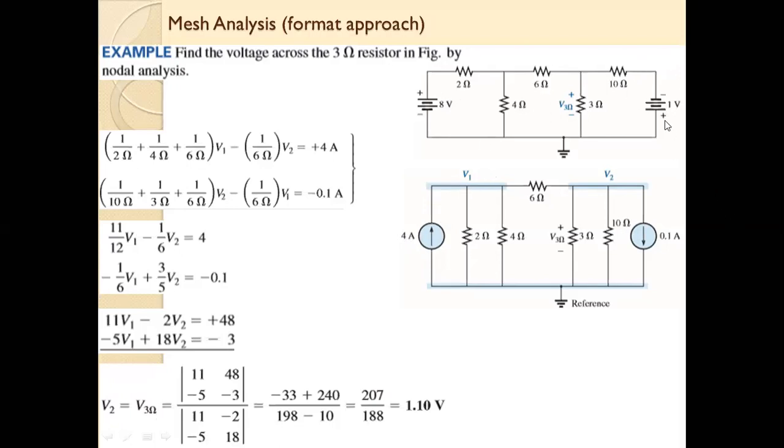Similarly, again here the voltage source is given. In this source, the conventional current direction is downward, because that is from plus to minus. So we will make the current source in parallel in the downward direction. And the resistor which is in series with the voltage source, we will place as it is in parallel. And the value of current would be found using I equals V divided by R. V is 1 and R is 10. So 1 divided by 10 is equal to 0.1 ampere, that we calculated. And the rest of the concept is the same as I explained.